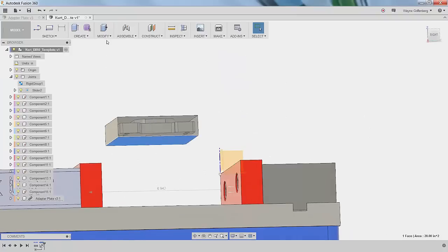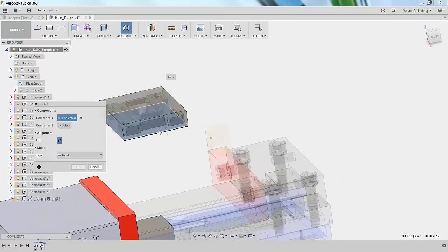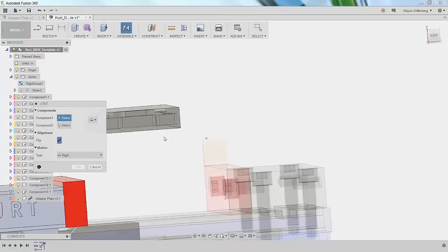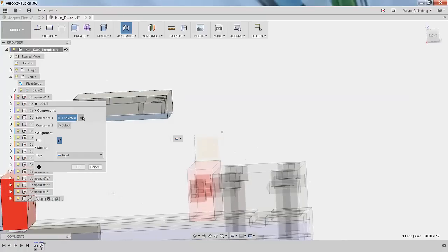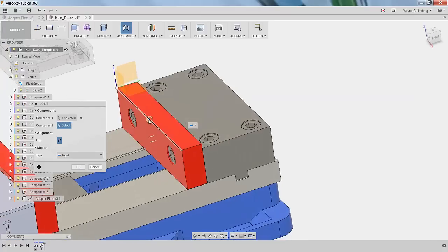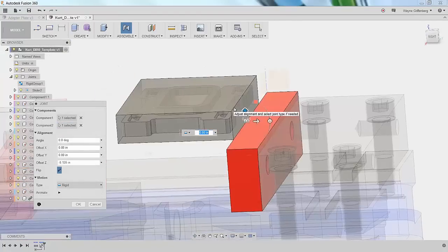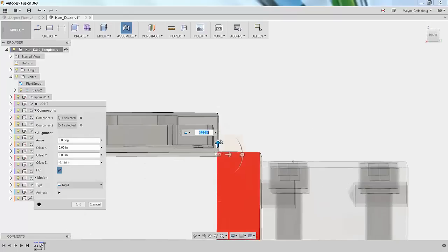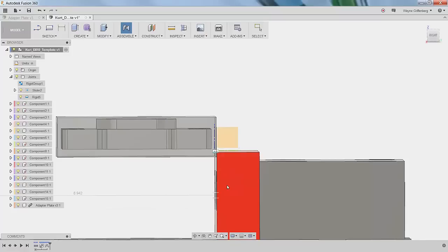So then we could do something like this. I can grab this face, and I can make that the assembly for my joint, and exit out of there. I can grab this face, and, oh, you know what it is? It needs to know where we're selecting the center at. And this face, like that. So now I can add that as an offset. And this is where I would probably do it better like this. Now I can stretch that down, and I can say I want that to be negative 0.125, and that's probably the better way to do it.